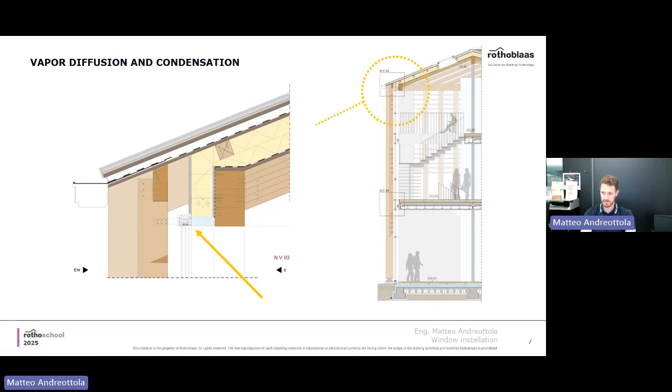What does that mean? Cold bridge is the first thing that you have to avoid while you're designing a window. And this is because even if you do every other thing in a perfect way, so you do the airtightness perfectly, you waterproof everything perfectly, but you have a cold bridge somewhere in your details, meaning this part here is colder than the rest of the surface, you are at big risk of interstitial or superficial condensation.